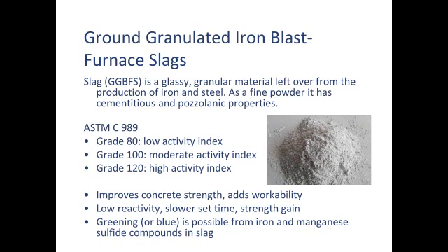And these sulfides, when they react with water and the alkalinity of the concrete, they can turn green. And I've seen slag cement look like seaweed green. It can look kind of nasty, and it takes time and air and oxidation for that greening to go away. Sometimes it looks bluish. That might take a few days. I've seen concrete where it doesn't go away. Some countertop concrete made with it, I've seen it go away too. But it's a possibility. It's a real possibility.